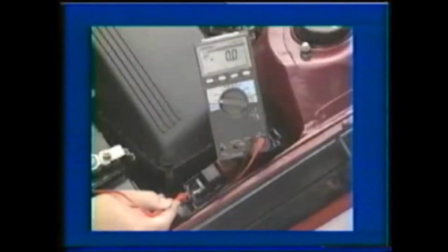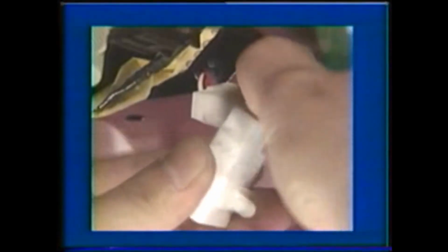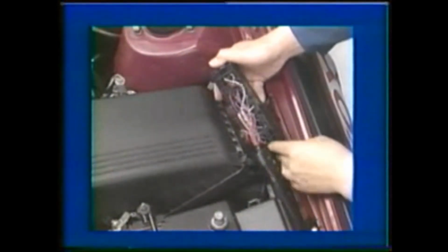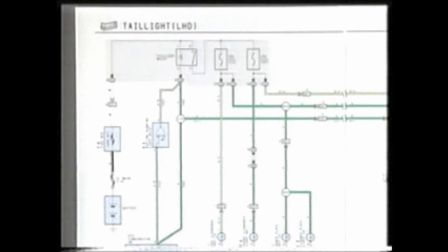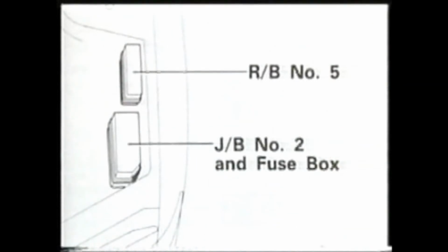As we have just seen in the two examples, by making use of the EWD, it is possible to do a considerable amount of troubleshooting before even touching the car. If you first study the system circuitry and location charts to gain a sufficient understanding of the circuitry, you can keep work to a minimum, thus saving time and avoiding replacement of incorrect parts. This is the sign of a superior technician.